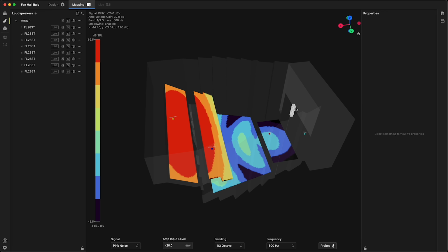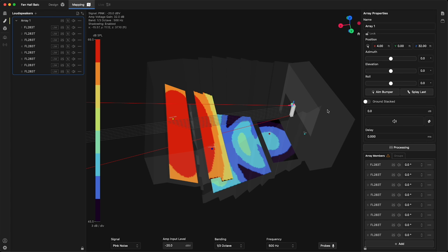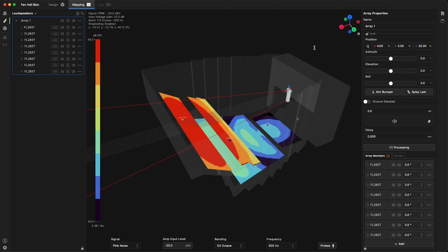As you can see, the line array is predictably focused on the balcony since we haven't splayed it. The individual center lines of each box are shown on these gray lines, so we can use that to aim things manually if we'd like. The upper and lower coverage angles of the top and bottom boxes are shown with the red line for reference.